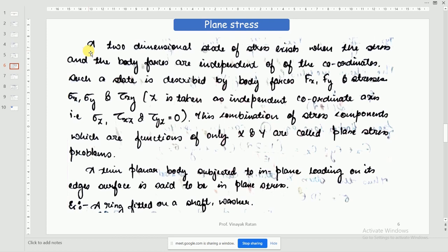I'll take that example and tell you what the phases in FEM are. I'll take a rectangular plate with a hole and pull it on both sides. Stresses will be there where the hole is, so I'll apply the plane stress condition for that in the software and explain the phases in FEM. Can you tell me other examples where you may apply plane stress conditions, which are not on the slide here?